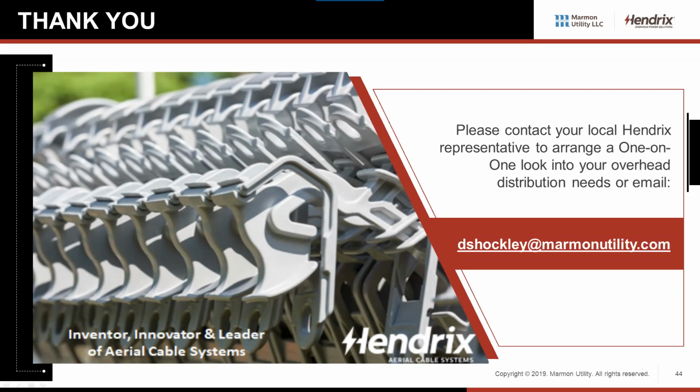The misconception is that we need to cover that up. When I hear people say, well, I was taught that I need to seal up that tap, to me, that is indicative of somebody that's taking what they've been taught about underground cable and applying it to this because they're both covered. This is not insulated cable. There isn't a ground shield on the outside of it like you'd have with underground. We use compact conductor that's overhead.